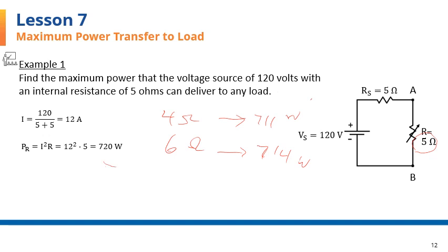You may have heard of impedance matching when connecting a speaker to an amplifier or connecting an antenna to a receiver. The reason for matching the impedance of the speaker to the output impedance of the amplifier, for example, is to have the speaker receive the maximum power possible from the amplifier.